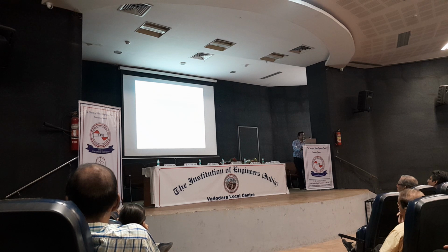Now, as I discussed, I'll try to divide my talk into two parts. One is related to how to deal with the software package, and the second is how to do the analysis, the load flow analysis. So whenever we are dealing with the IEEE 5 bus, some information is with us. That information is in terms of transmission line data. Whenever we are dealing with transmission line designing, we need 4 data: resistance, reactance, susceptance and conductance. As per the standard, these data are available on the IEEE website.